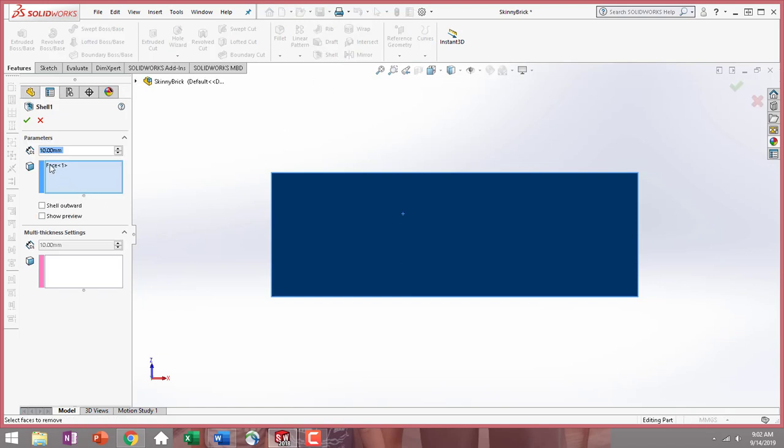You can see that I need to put in a depth, so we wanted this value or dimension to be 1.5. The cool thing about the shell feature is it will shell the entire material, so that wall thickness that is left will be 1.5 everywhere. This includes inside the knobs if we go too deep.